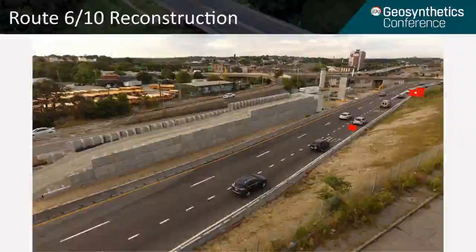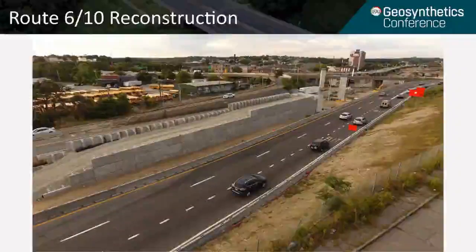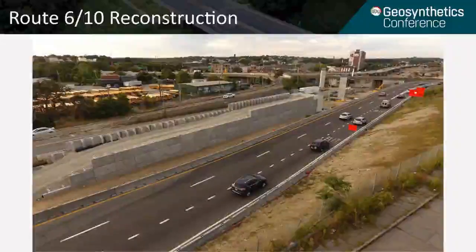And the reason that lightweight fill had to be used within these ramps is because of a large diameter 100-year-old brick sewer and some challenging subsurface soils. The utility owner told the DOT that no additional loads could be imposed on the subsurface utilities by the embankment.